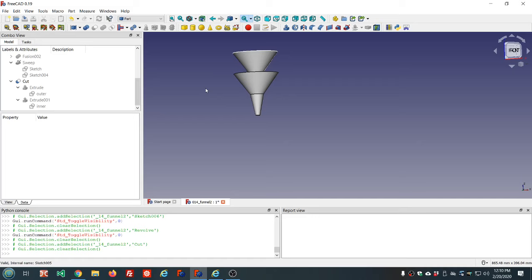Maybe there's some seam lines can sometimes cause a problem. Two seam lines converging. Coplanar faces can cause problems. And you can have some problem, for example, with the revolve, and it's just not working. So knowing how to do it from a different way, a different tool, for example, using the extrude instead. Just knowing all the different ways can help you get your project done.